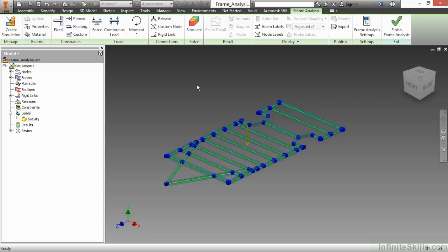Inside of this, we have a node-based FEA environment, where it takes the end treatments and the existing members that we have and creates these rigid links between them so it understands how these members go together. You don't have to say that that part is welded. You can just say that it has a rigid link. You can also adjust your links by releasing degrees of freedom, creating custom link information, or applying a manual rigid link where no one existed before.